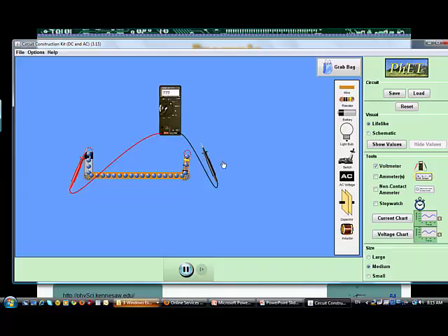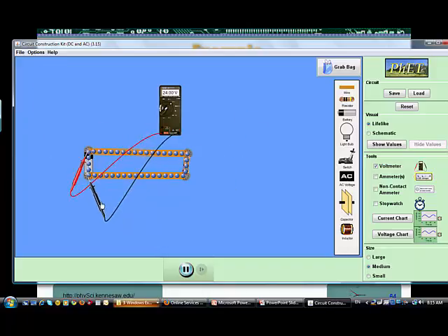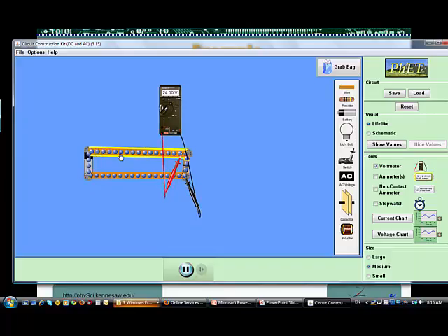Okay, now I'm going to remove this for a second, and I'm going to connect a wire from the other end of the battery. Now we have a current flow. So again, this is an ideal battery. So for an ideal battery, I still read 24 volts. I should still read 24 volts throughout here and throughout here. This wire here should have the same electrical potential, 24 volts. Now the voltage drop is across the resistance.